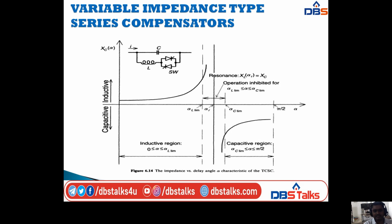So here, the inductive region, the resonance, is where XL of alpha is equal to XC. In this operation I indicated alpha is in between alpha L limited and alpha C limited. On the left side we have the inductive region, and on the right side we have the capacitive region. The inductive region is alpha from 0 to alpha L limited, and the capacitive is alpha C limited to pi by 2 range. Here alpha is in between 0 and pi by 2.